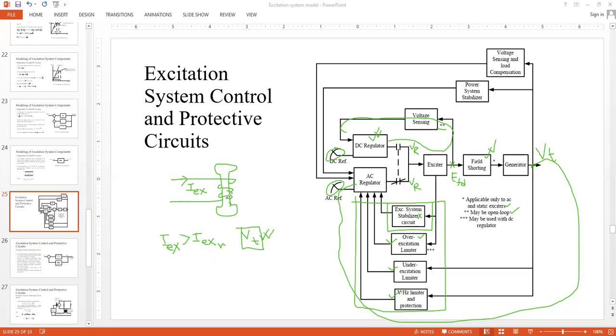This coil would be carrying overcurrent, and if it carries overcurrent beyond its rated value, of course, it will be heated, right? So the field coil heating will occur. So heat generated in the field coil, that is the problem. Terminal voltage would not go beyond a certain value because of saturation. Remember? Yes, there is saturation. So if this happens, probably there will be saturation. Flux would be saturated.